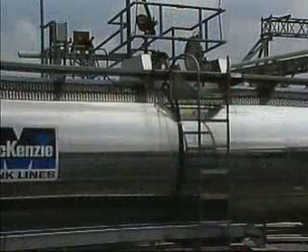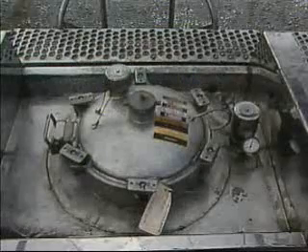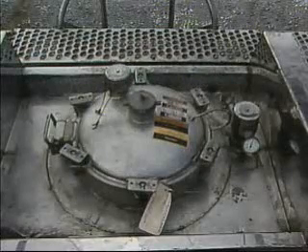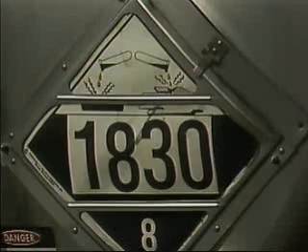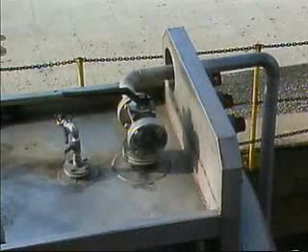He checks the safety attachments on the truck, including the handrails and ladders. He also makes sure that all valves and vents are in good condition, that all placards are accurate and in place, and that the product outlet valve on the truck is tightly shut. During the inspection, the operator also checks that the loading arm on the loading rack moves freely, that the proper hoses are being used, and that there are no leaks in the system. If pumps, compressors, or vapor recovery equipment are used, he also makes sure that they're in good working order.